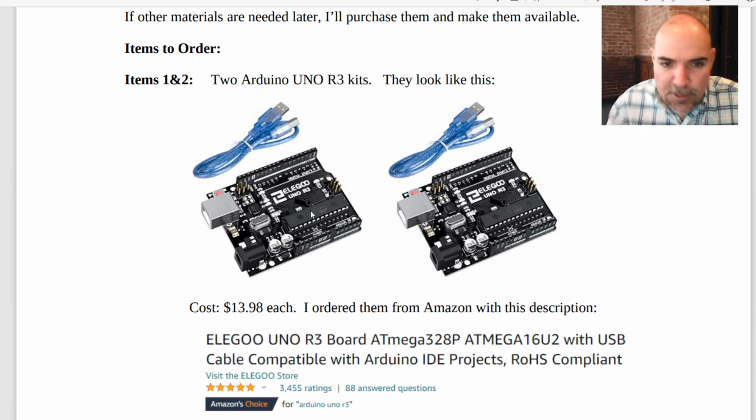And really, feel free to shop around and find these at a cheaper price if you want to. But the ones that I bought were these Elegoo ones from Amazon, and they work fine. They're actually pretty high quality, and they work well. The other nice thing I like about these, other than some cheaper ones, is notice that the pins are labeled on the plastic header connector here. Which makes it easier to do the wiring. It's labeled actually on both sides of this, so it's easy to see. I have had some cheaper ones of these, cost a few dollars less, but the black plastic here is not labeled at all. It's labeled on the board, but not on the plastic, so it can be more confusing when you're wiring them up.